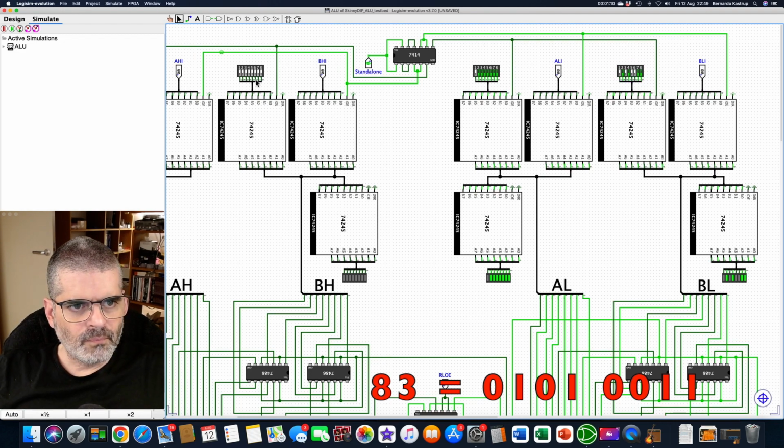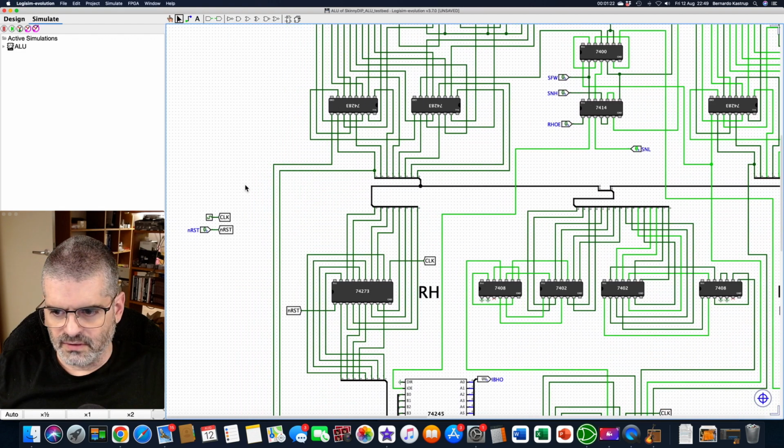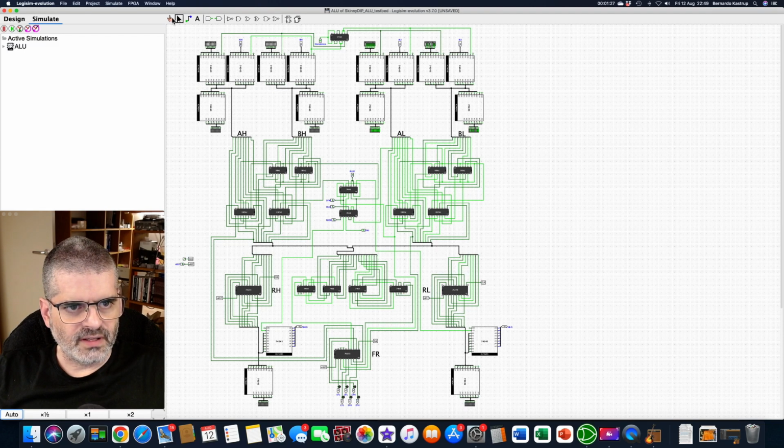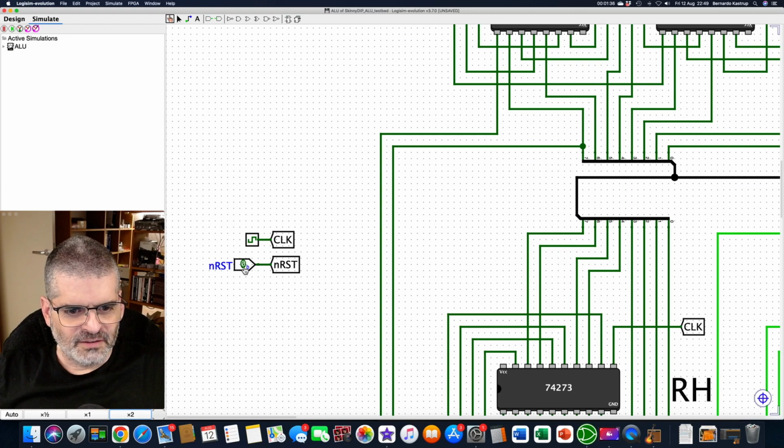And then we go down in here. Oh yeah, set negative low is already set. So that's already done. And then we go to these two here. Let me put it in auto, then we can see everything. So now the system is in reset. Reset is 0. Let me show it to you, otherwise you can't see it. Here, reset is active low, and it is low. So we just do a reset cycle, and I'll bring the system out of reset.